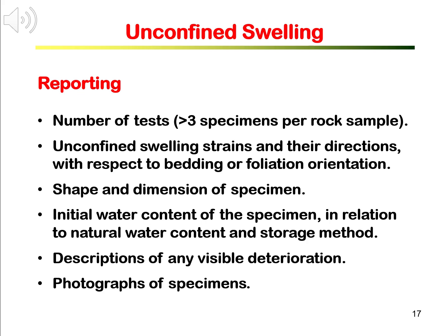Tabulated values of specimen dimensions, swelling displacement readings from the micro gauges or LVDTs, calculated unconfined swelling strains and their directions with respect to bedding or foliation orientations, and descriptions of any visible deteriorations of the specimens.